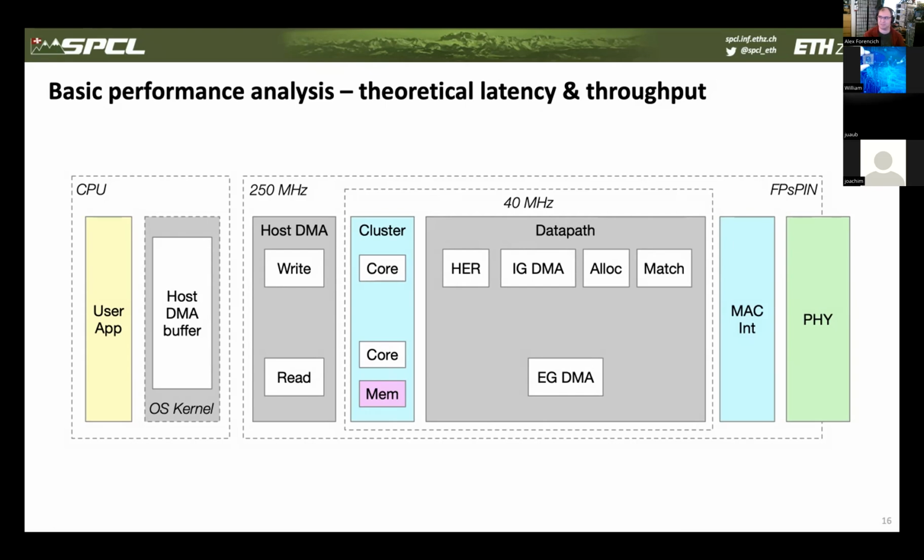I think he was also using the VCU 1525 actually, because I picked up several of those off of eBay a while ago. But it also runs on the U200. It took a lot of work to get things operational at 250 megahertz, but the whole data path on those runs at 250, including the cores. Oh, that's neat. And they're using the Vex RISC-V cores. That one can actually handle traffic into the cores at 200 gigabits a second, right? If you saturate both of the 100 gig ports.